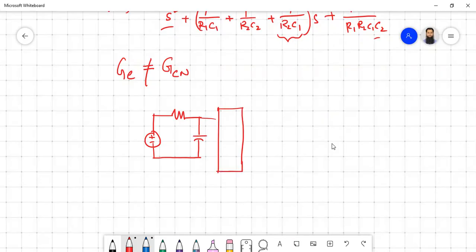This is your amplifier K. The properties of your operational amplifier are that Z in is actually infinity, very high input impedance. What does it mean? There will be no current flowing in this way, I should be zero. And what is the other characteristic? Z out should be zero. So it will be just acting like a voltage source from this side.